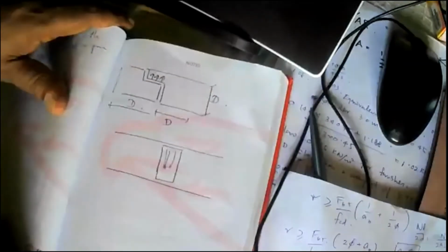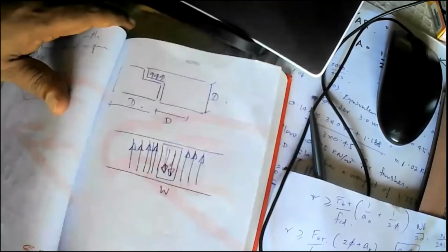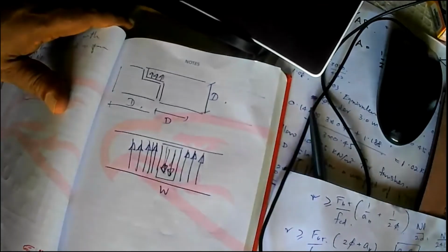So at this place, we are getting a big load transferred. You will find that in the main beam, in this region, the plane sections may not remain plane. So if this is the case, then you have to provide a lot of links around it to make sure whatever load is in this particular beam is resisted by all these links, and transferred to the top of the beam, because generally we consider that beams are loaded from above, not from the bottom.